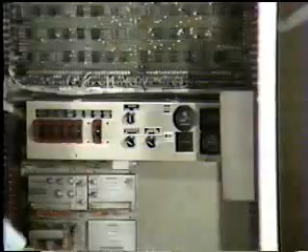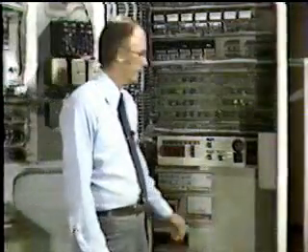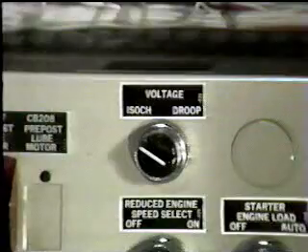The AC control system monitors and controls generator output. The AC system makes adjustments in the exciter field during operation to increase or decrease generator output with change in load. The voltage regulator has two operating modes for controlling generator output. When the voltage regulator is placed in the isochronous mode, the generator's output is kept constant with changes in load. Generator output, however, will change with load demands when the voltage regulator is in the droop mode.